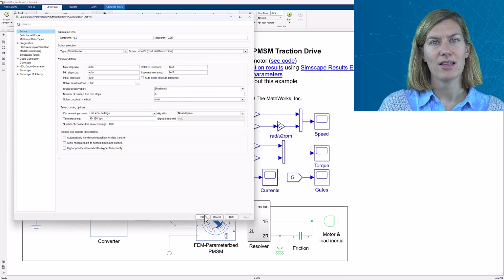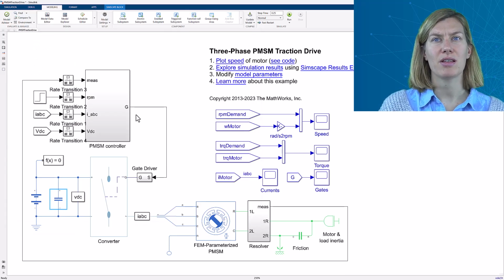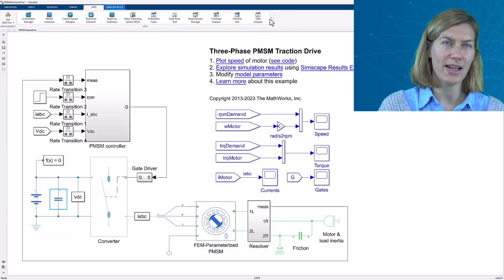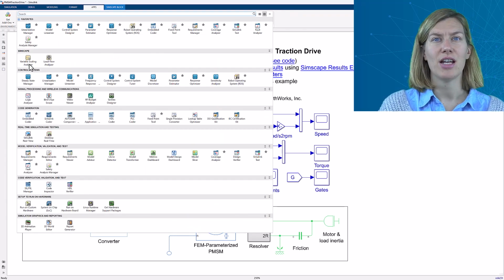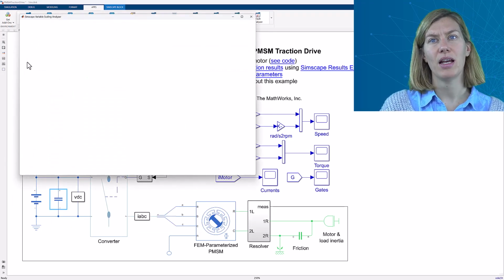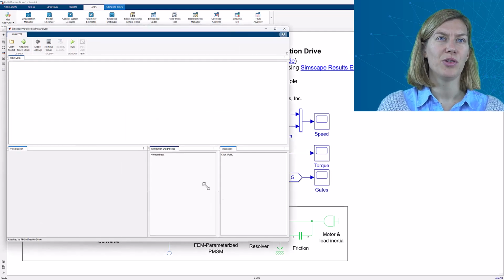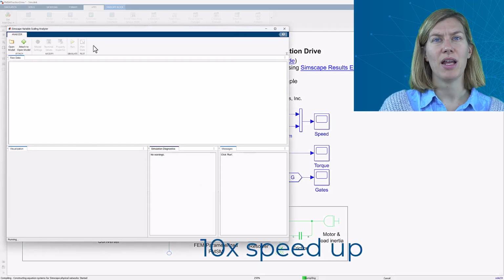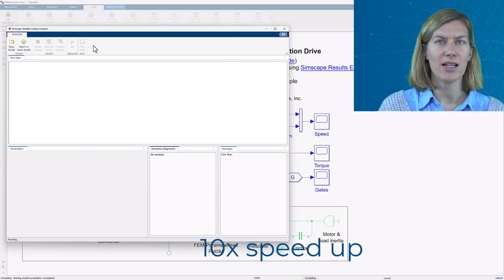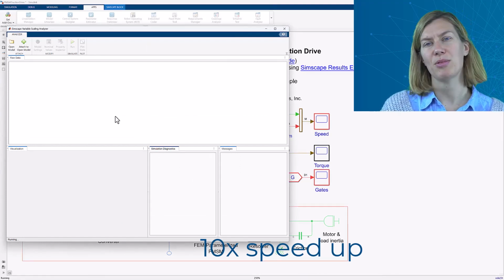To now analyze the effect of the variable scaling using the simulation results, open the variable scaling analyzer. If needed, attach the tool to the current model and run the simulation from here. Using the results, the app will display an analysis of the simulation states with respect to each other and the absolute tolerance value.